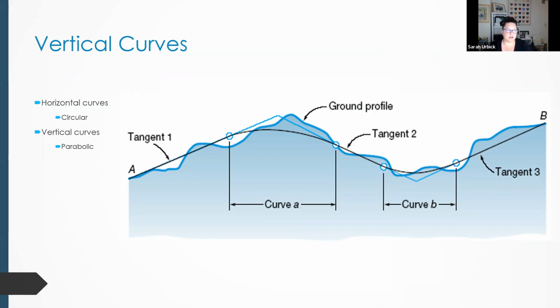Couple examples, I'll try and get the pictures in a little bit. The Tehachapi grade. What's interesting about the Tehachapi grade is not that it is so steep, it is that it's so long. And what it does is it's a railroad track system. The railroad comes through, the train comes through, and it actually does a complete circle and circles back underneath itself. And it's to stretch out the amount of pull that the train has to maneuver, has to manage.